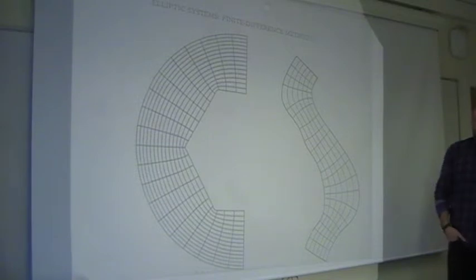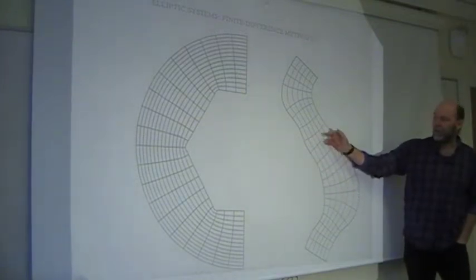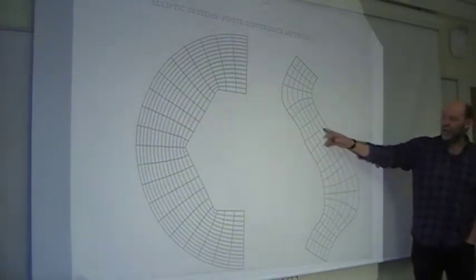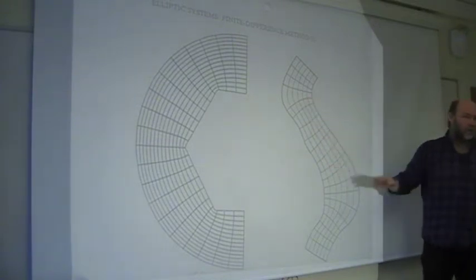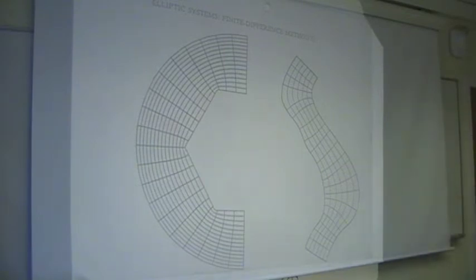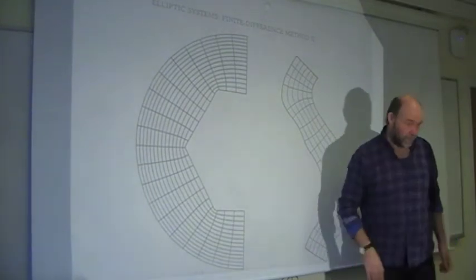Just solve the Laplace equation for the stream function and the potential function. And you have the stream lines and potential lines. And what's nice here, you will have an angle of 90 degrees on all the cells. So they will still be perpendicular, which is, in many schemes, quite essential. If you don't have it, then you will have something you have to adjust with the transport in and out of the cells. But still structured meshes.